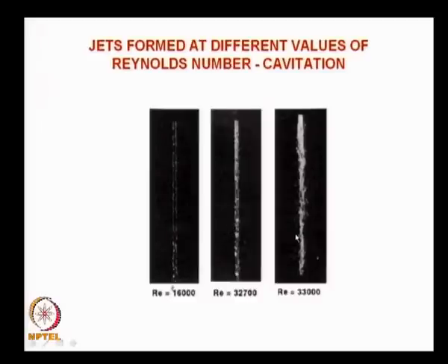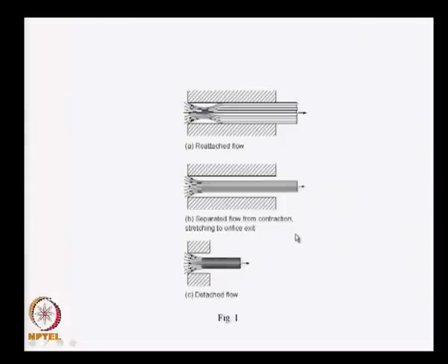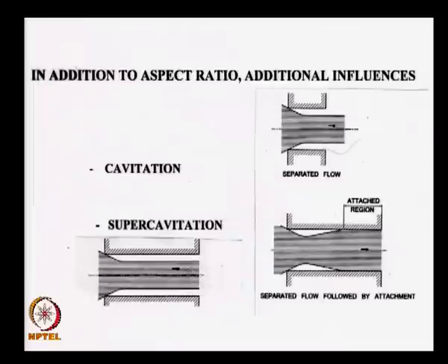At some Reynolds number it becomes violent, some changes like this. What are these things about? Let us try to understand some of this. When I have an orifice, I have Vena contracta here, flow attaching here. Sometimes even for the same length the flow goes straight, it does not attach, whereas for a small length it is understandable, because if I cut the orifice here, there is no way of attaching. But this also takes place. What is the reason for this? Let us put it down.